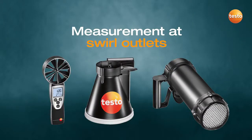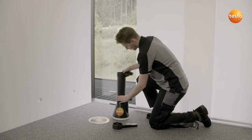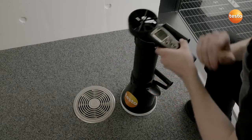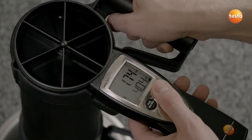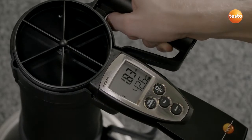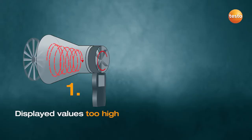This is how you measure properly at the swirl outlets. Measuring the volume flow accurately at swirl outlets is often a challenging task because the supply air is fed into the room in a circular motion, making an accurate measurement difficult. Why is that? Vanes can only record the flow accurately if the airflow hits the vane vertically. The flow straightener ensures that the airflow passes over the vanes in a single direction. Let's take a closer look at what happens.